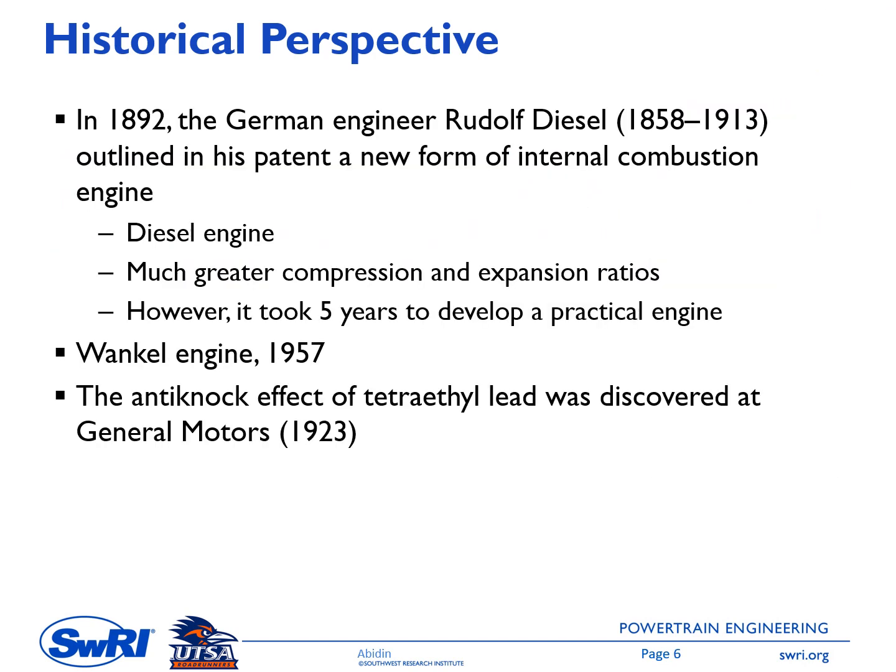Until around 1890, the developed engine was based on the spark ignited engine. It means it required an external ignition, in this case a spark plug. And then in 1892, the German engineer Rudolf Diesel outlined in his patent a new form of internal combustion engine. We call this one the diesel engine till now. In this case, he operated the engine at much greater compression and expansion ratio.